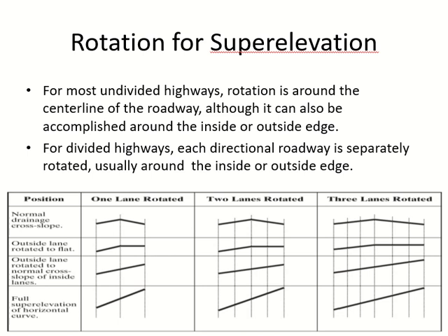Okay. I am changing the slope. Changing the slope means I have to change elevation, right? Elevations are changed according to some reference. For superelevation, your reference can be the outside edge, the center, or the inside edge. One of these 3 could be the reference. The most common is center. Changing this elevation and the slope is called rotation. Rotation means changing the slope or the elevation. Clear? Okay.